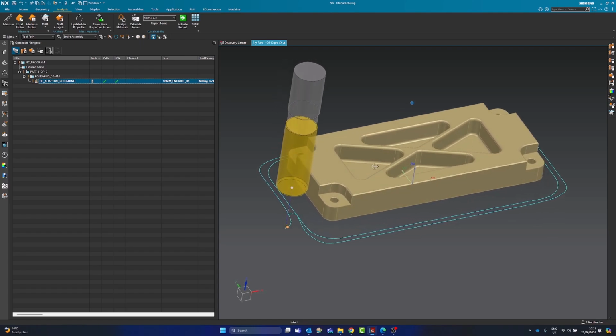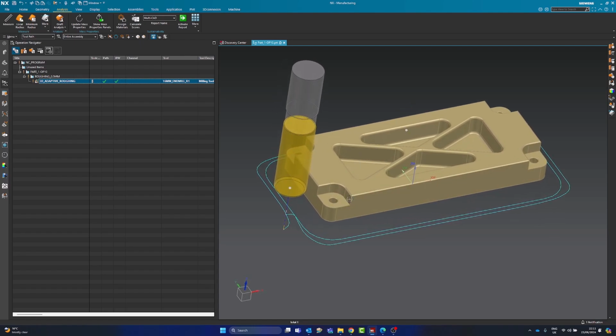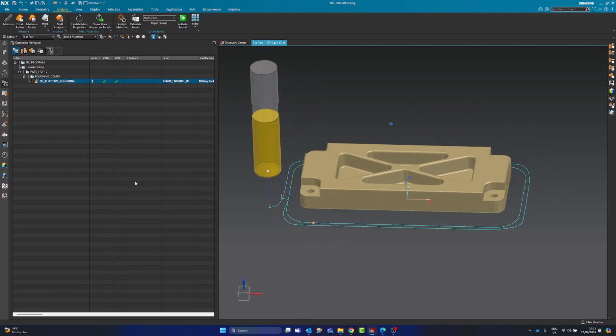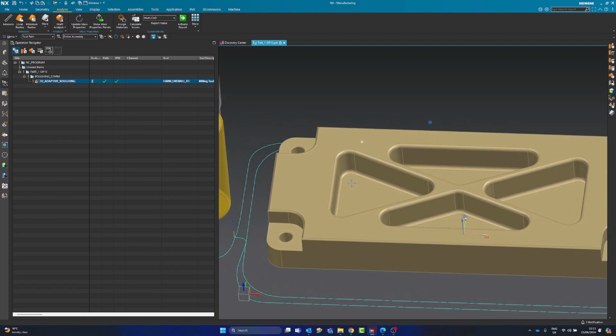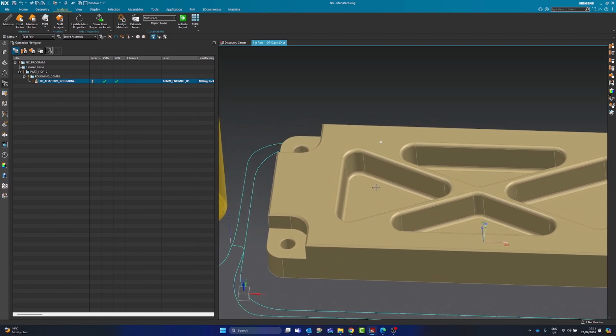Now I need to come in and rough these pockets out, and I need to rough these little corners out. So thinking about it, the way I would like to rough these pockets out, again, you've got a couple of options. You have got a cavity mill where you can do level by level. To me, adaptive mill makes sense. I would like to rough down here and take it all out in a trochoidal pattern.